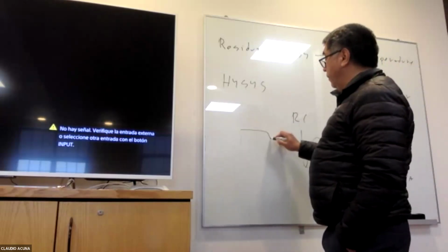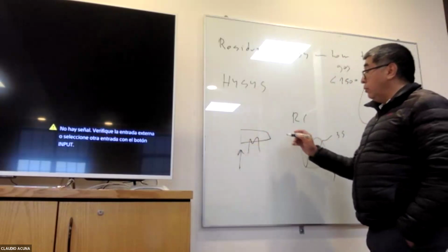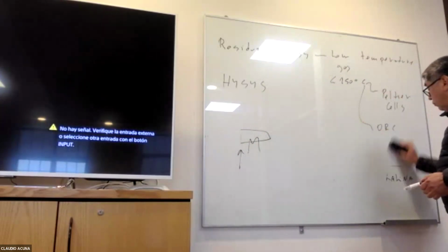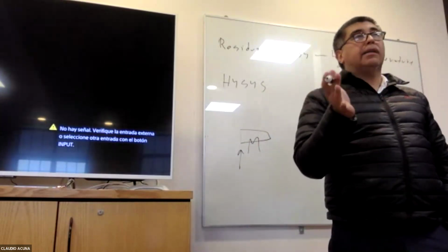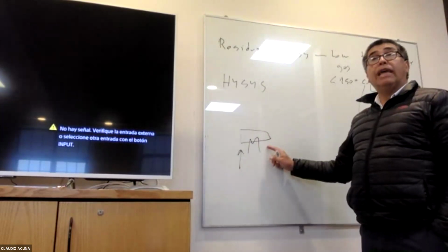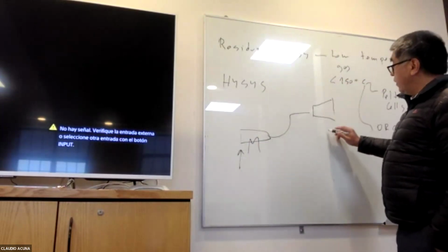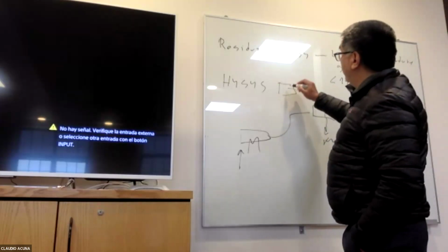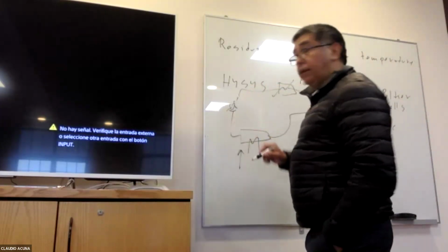So you will start with thermal energy, whatever thing you do. I need to write it down, but just to have the idea here, you will evaluate different fluids. We can assign different fluids. The one that I want to do is step by step, because it's easy. You start with a heat source, and then that goes to a turbine, and then you will generate power here. You will see the kilowatts that you're generating. Then you need to remove the heat. You need to have a condenser, and then here you have a pump, isn't it? To put it back here. Okay.